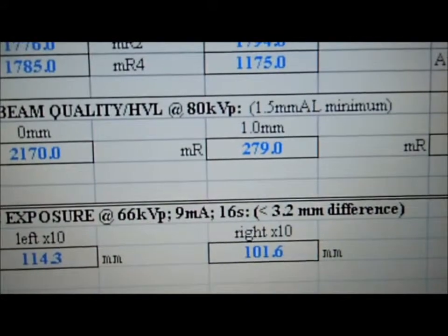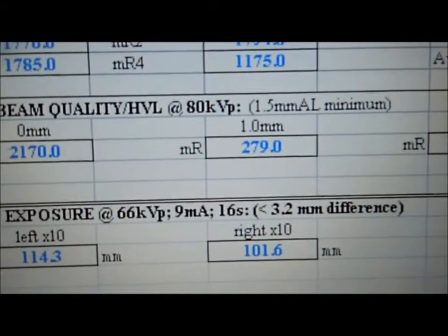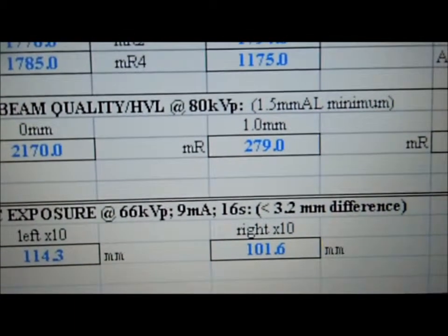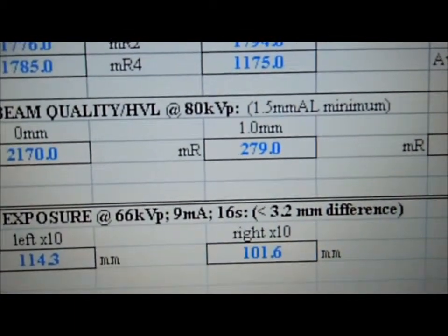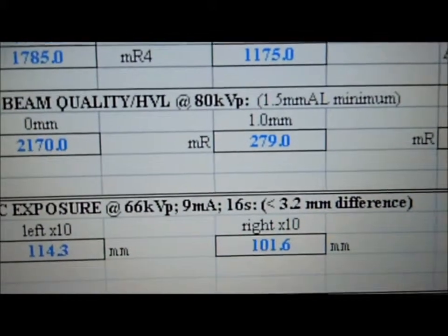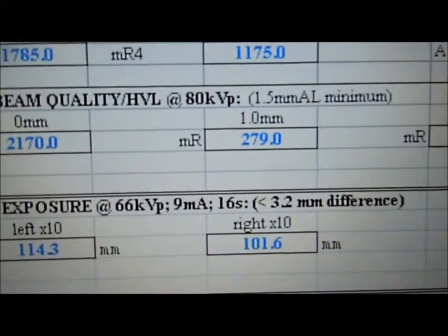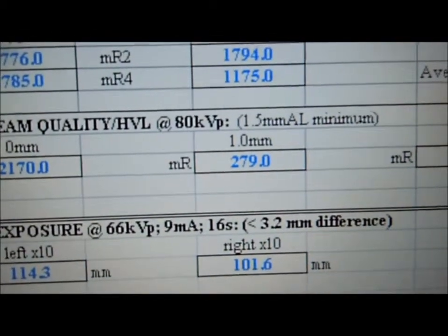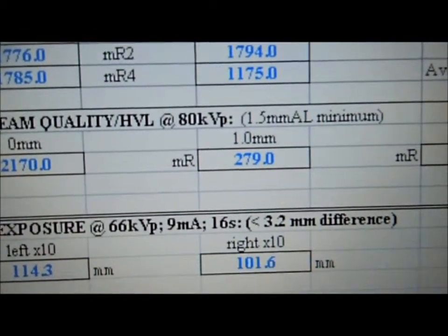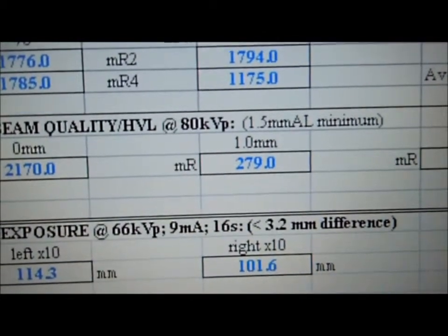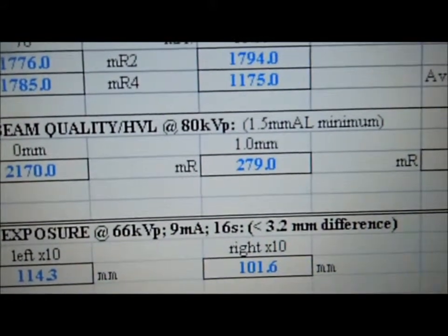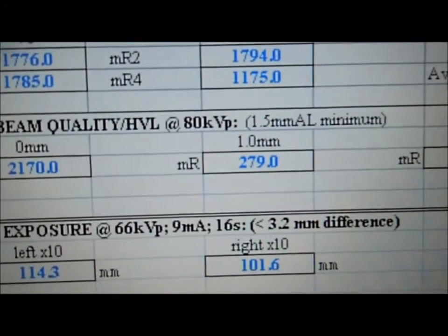Second application of half-value layer in an imaging department has to do with room shielding. Rooms that contain fixed X-ray equipment are typically shielded with lead-lined walls to reduce the radiation exposure to workers and the public from the use of X-rays within that department. When designing the shielding for a room, the physicist will perform calculations based on the half-value layer of the X-ray beam. In general, the design will call for enough half-value layers of shielding to reduce radiation exposure outside the room